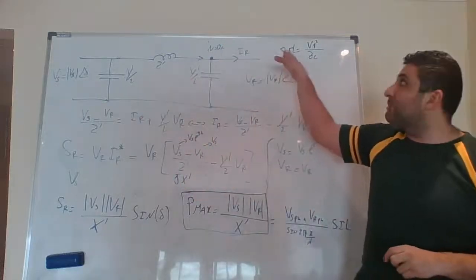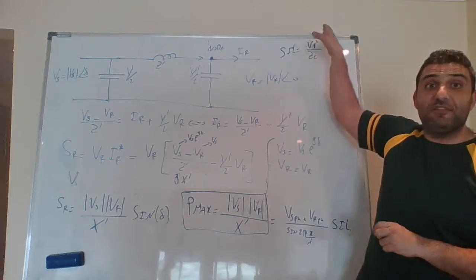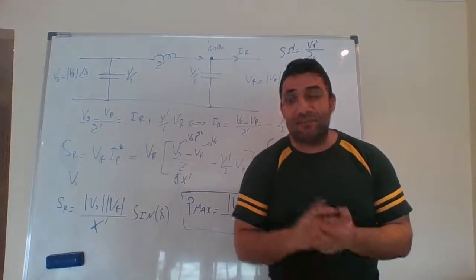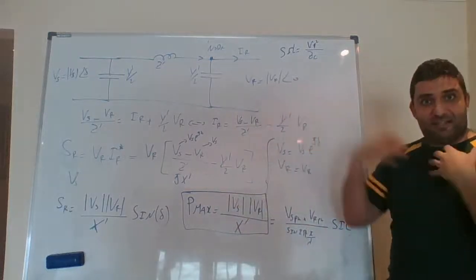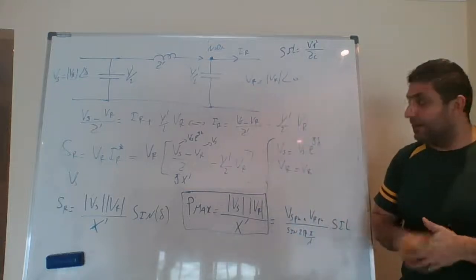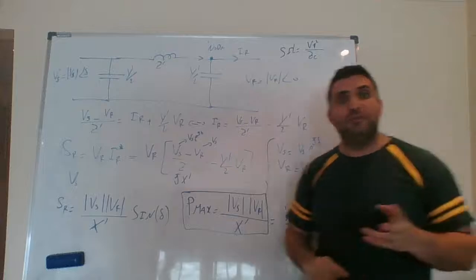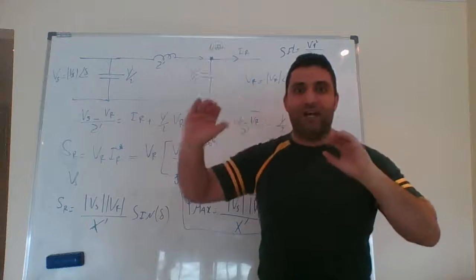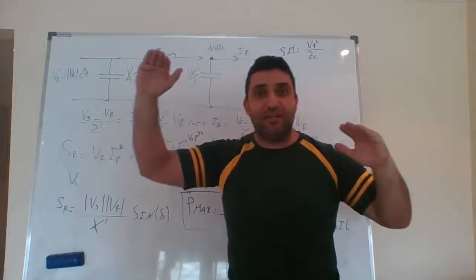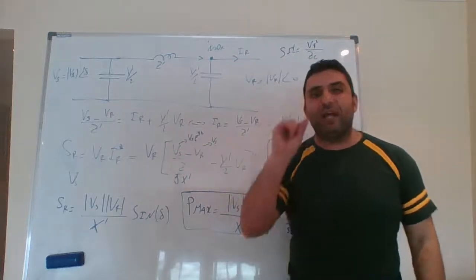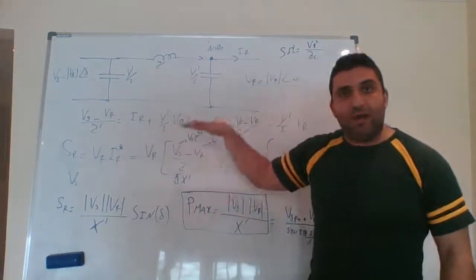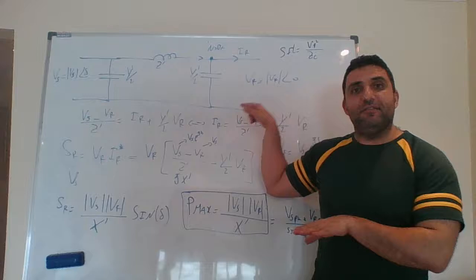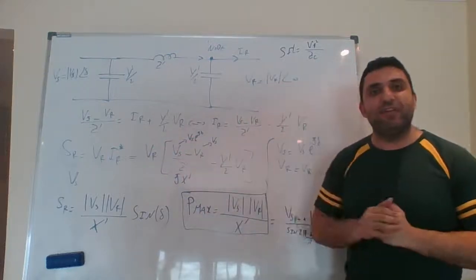And then I saw that surge impedance loading is V receiving squared over ZC. V receiving squared is basically the rated voltage of the system, because I always take it as a reference. And then after I did this, I found the voltage profile. If I have the voltage above the voltage sending, I look at it, hey, it's at no load or a very light load. If the load is very heavily away from the surge impedance loading voltage, I look at it as a heavily loaded system.